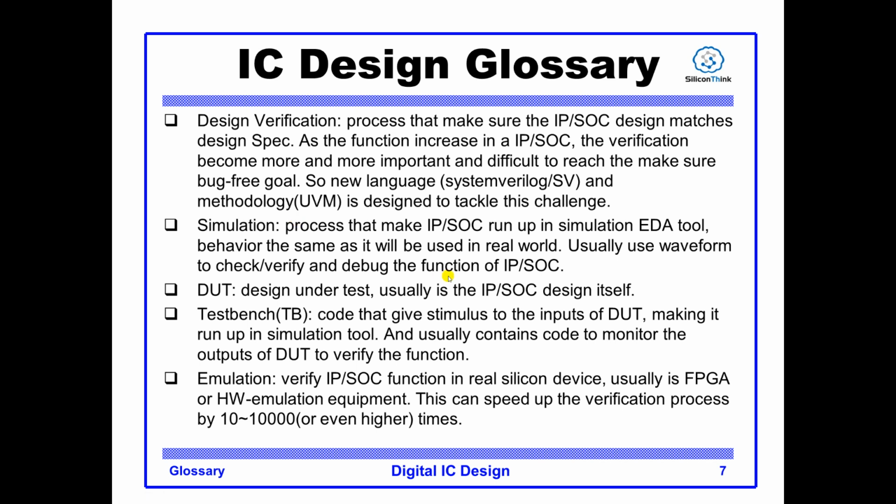Simulation. Simulation is the process that makes your actual design run in simulation tools, behaving the same as it will in the real world. Usually we use waveforms to check, verify and debug the function of the block. DUT, design under test, usually is the IP or SoC design itself.